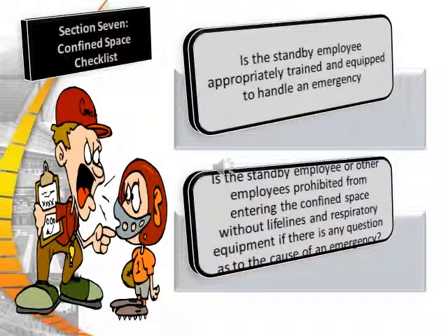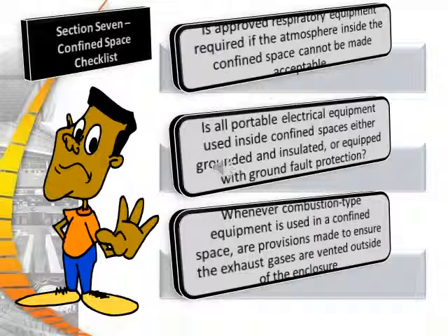Is the standby employee appropriately trained and equipped to handle an emergency? Is the standby employee or other employees prohibited from entering the confined space without lifelines and respiratory equipment if there is any question as to the cause of the emergency? Is approved respiratory equipment required if the atmosphere inside the confined space cannot be made acceptable?